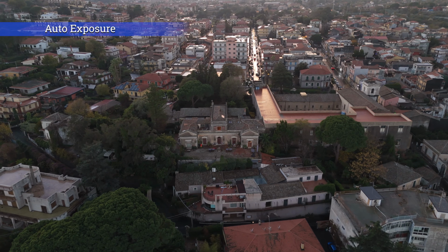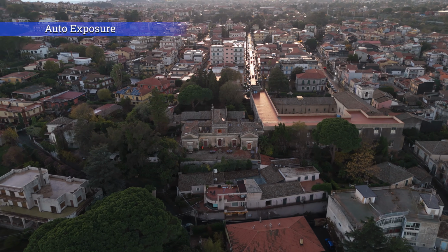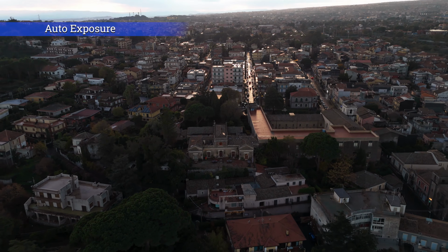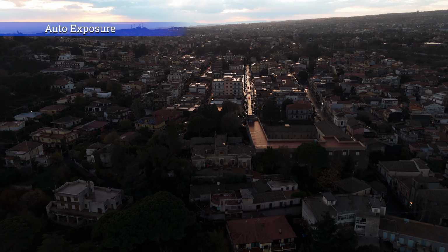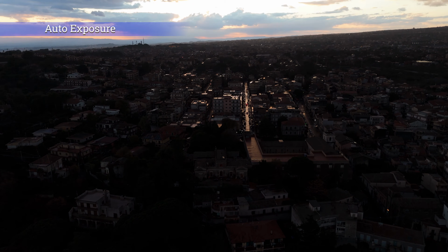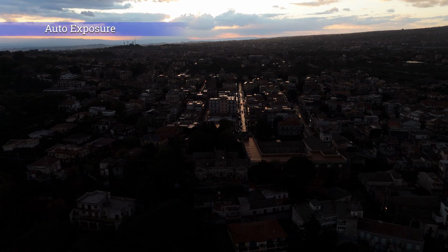During each MasterShot, the aircraft and the gimbal perform all sorts of movements, with the camera alternating top-down views to others facing forward, including the sky. This leads to important shifts in luminosity. For good results, it is crucial to expose correctly. Beginners generally start by using auto exposure, but in this mode the software will compensate for the difference in luminosity, thus creating noticeable shifts in the brightness of the footage. A clear sign of an amateur job.